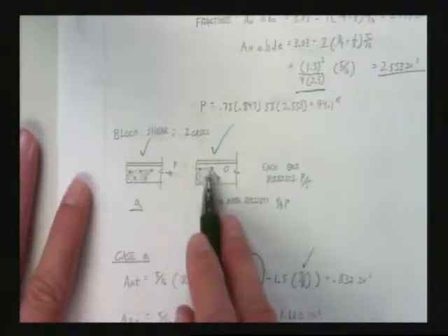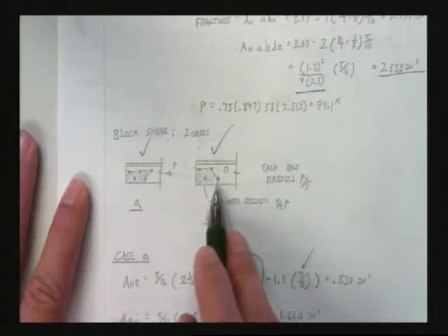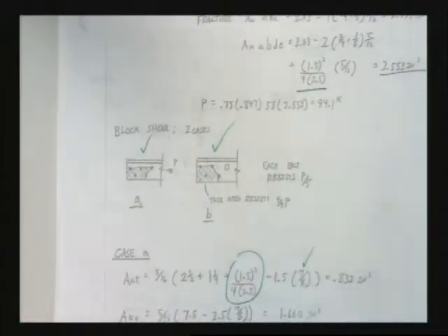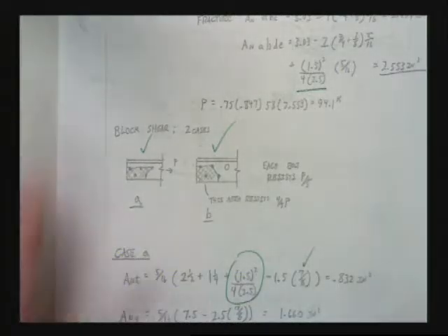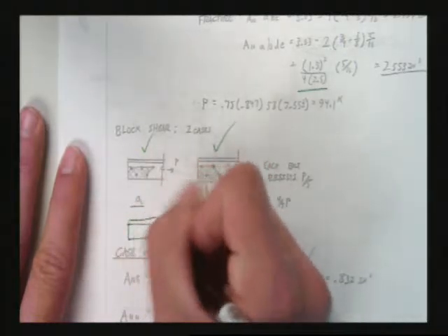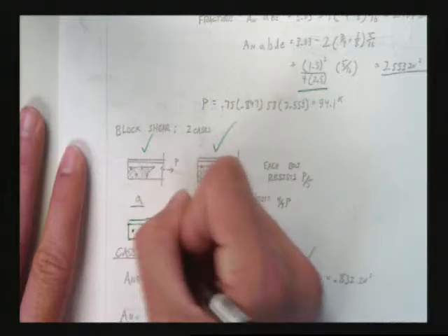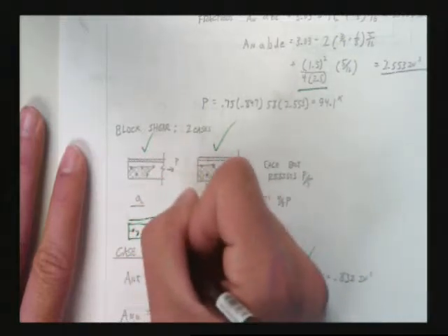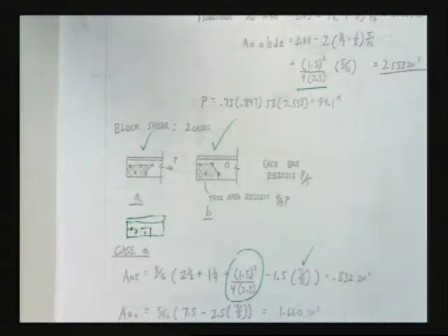Now I check case B. Over another diagonal and down. Now, it's hard to tell when you're just getting started what's going to control. It's hard to tell actually if there's another case you could check here. Hole, hole, hole, hole, hole. Fracture, fracture, fracture, and then go straight across. Right? Is that possible? It is. Should it be checked? Sure. Sure it should be checked. Run the numbers. See what it says. Okay?